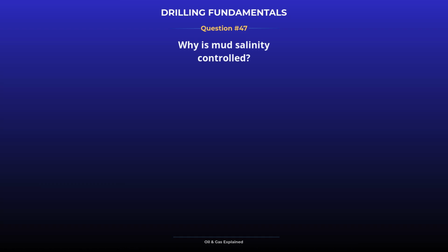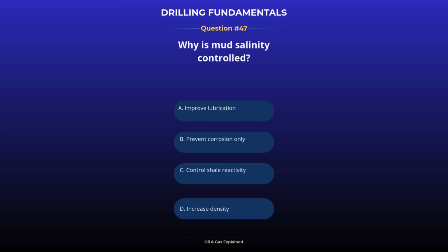Why is mud salinity controlled? Proper salinity helps prevent shale swelling and wellbore instability.